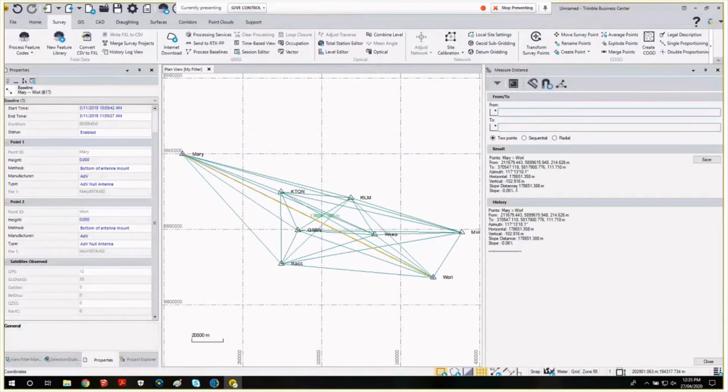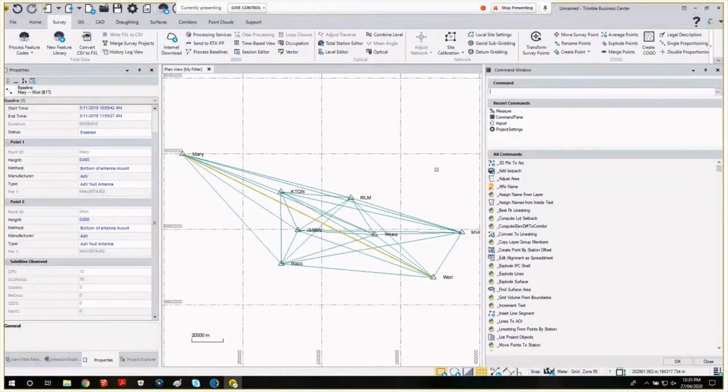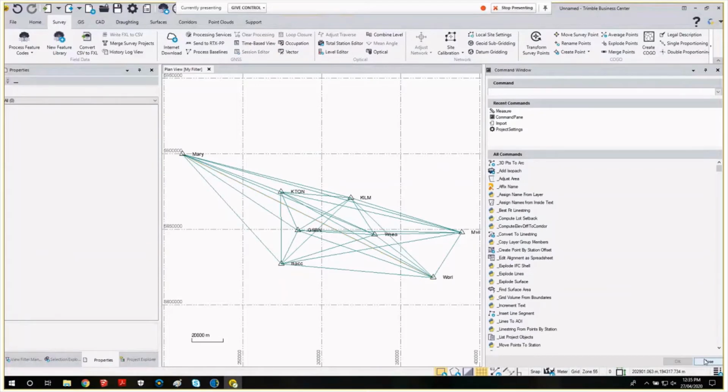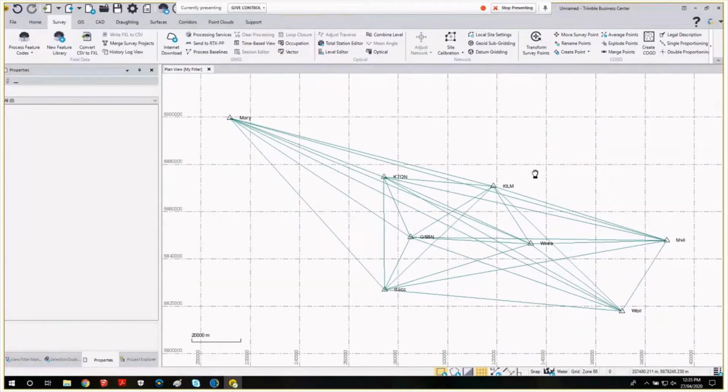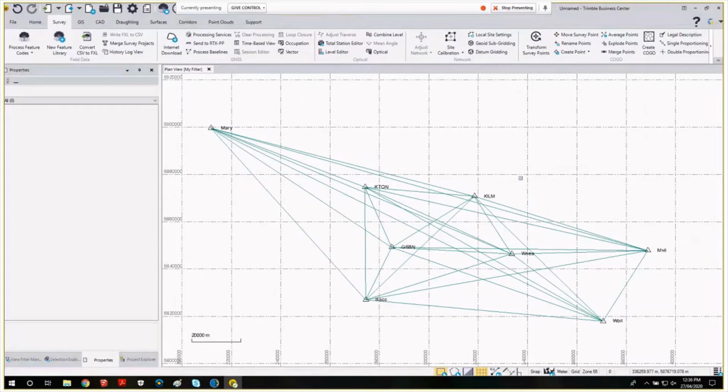Measure from here to here. We're looking at almost 180 kilometres, so it wouldn't be our best case of processing that. There is a diminishing result that you achieve with any GPS, and that usually correlates to an additional 1 part per million, so a millimetre per kilometre, and we would be adding in about 180 millimetres potentially in that processing compared to a baseline of 1 kilometre long.